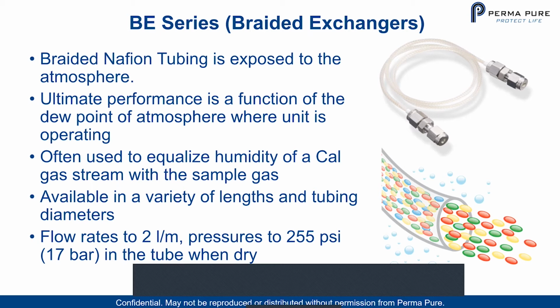What we do is we injection mold a polypropylene end in various types of sizes, shapes and connector designs, but basically the concept is that we're taking the polypropylene and we are encapsulating the polypropylene netting, and what that does is provide a very strong strain relief, where we provide a plastic attachment where we can attach a connector, as shown on the picture there at the right.